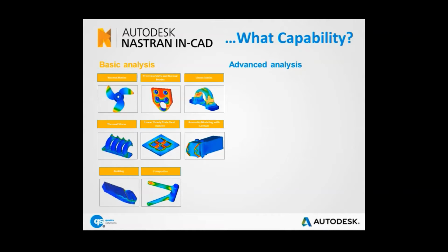You also have buckling, which could be a popular one. It assesses the stability under load and examines for sudden failure modes caused by compressive forces. And finally, on the orange side, we have composites. It provides straightforward handling of ply data, and analysis based on the latest test failure indices, as well as reliable linear and non-linear results. So non-linear being after the point of failure. Indices like PUC and LARC02 mean reliable and insightful results as well.